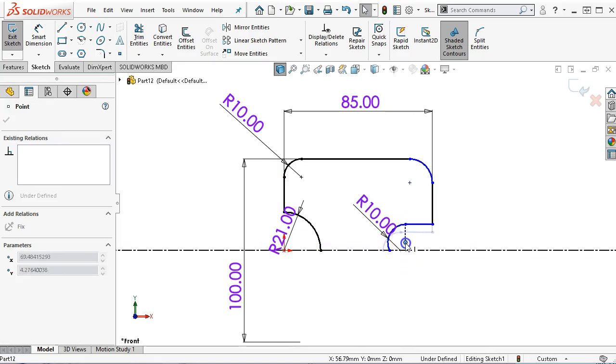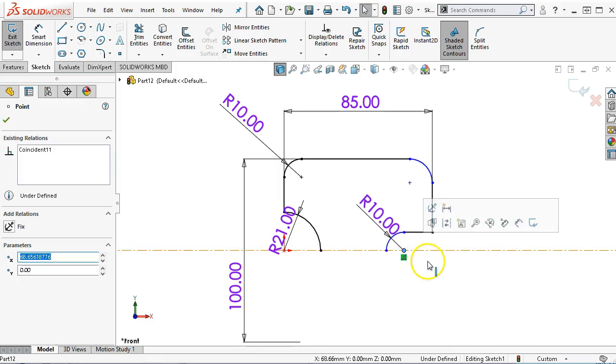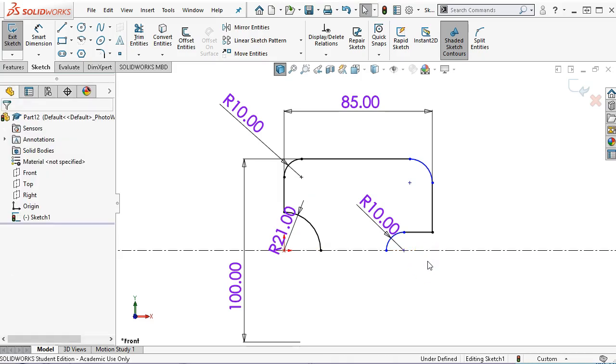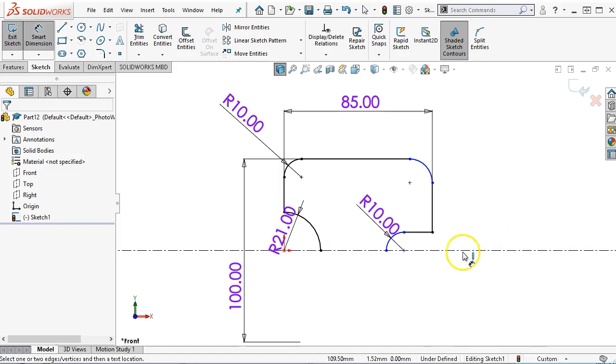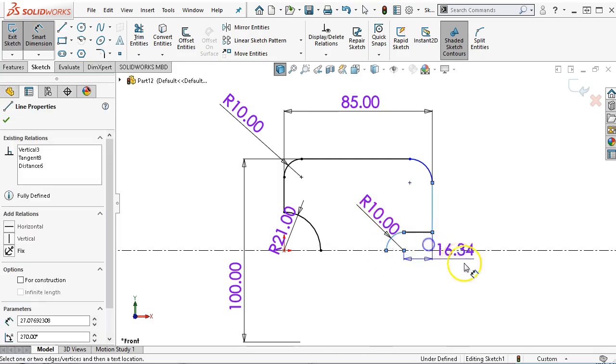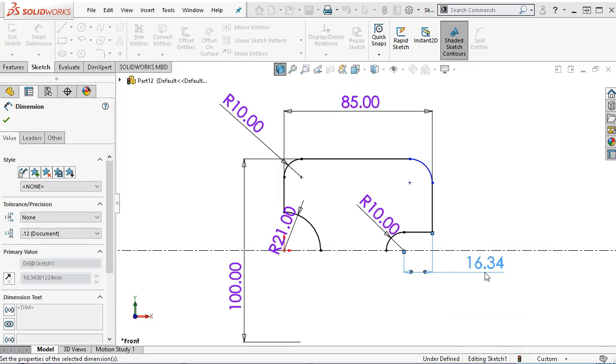There was a little bit of a hint that the center point didn't make it coincident. Usually it's just enough off that something looks strange with the arc, and then we'll go back and check it. So now that I've placed it on the center line, let's go back into our right click and smart dimension. The center of the radius is 25 from the edge.